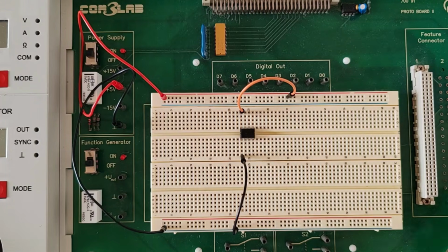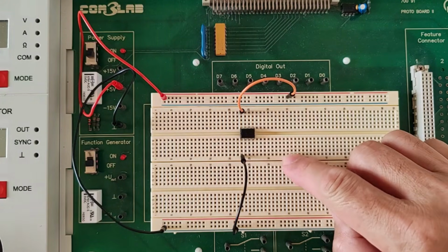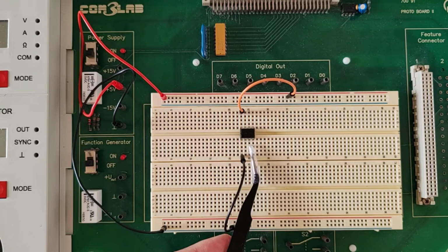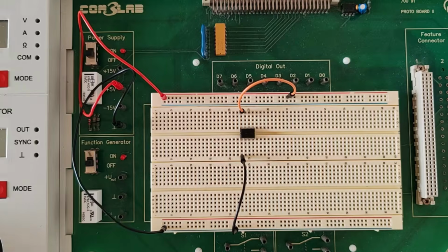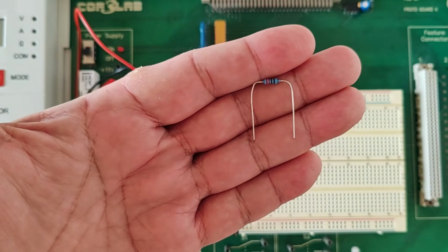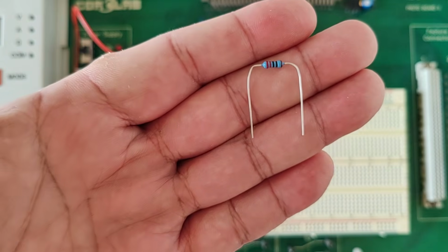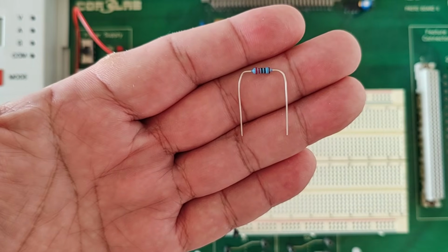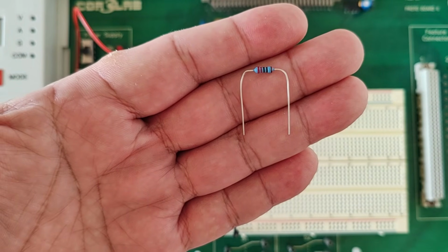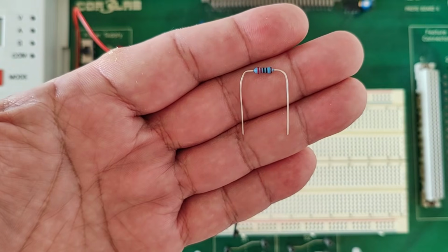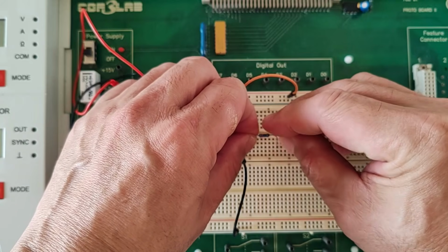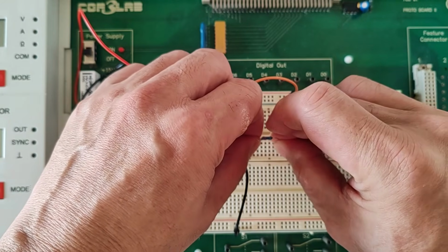Okay, now let's establish the output part of our Astable circuit, Astable Multivibrator. The output pin of our 555 timer is pin number 3. This one, pin number 3. On the output, based on the schematic, I would need to connect a 220 ohm resistor. I have it here. How do I know this is a 220 ohm resistor? You have to take a look at the color on the body. I'll refer you again to my resistor color code video in my channel, Derictronic, for reference. So 220 ohm resistor to be connected on pin 3. Let's do that now.